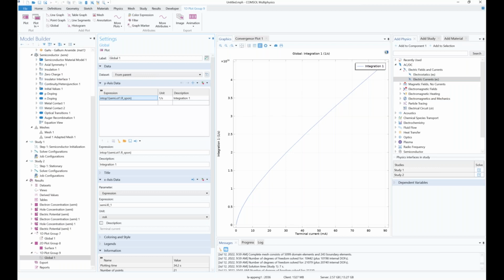When you have an electric field, then those electrons and holes will move. Also, the diffusion is driven by the concentration. When your electron concentration is higher in one place and lower in another, then electrons will move from the higher to the lower direction. So this is what we call the drift diffusion equations. You solve this in a more classical way, not a quantum way.